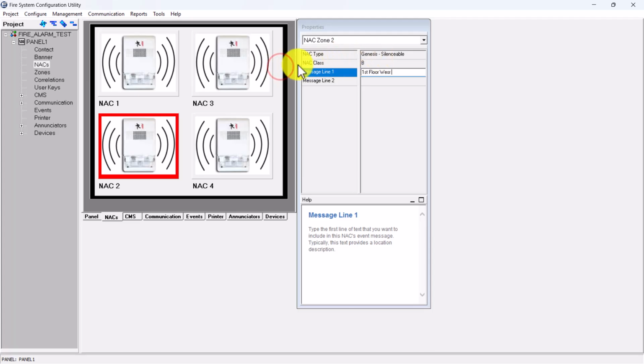Also with the supervisory, there's a couple different point types inside supervisory. We have remote drill, remote reset, remote signal silence. Since this is a CT1, it could cover multiple different point types from smoke, pull, any. You can hook up non-addressable devices to a CT1. That's what I'm using it specifically for, water flows and tampers.